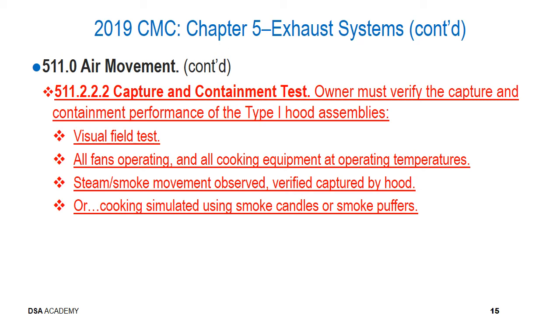Also associated with air movement is a new section, section 511.2.2.2, which addresses requirements for capture and containment tests that are now required for Type 1 hood exhaust duct systems. And generally speaking, the owner is required to verify the capture and containment performance of the Type 1 hood assemblies.